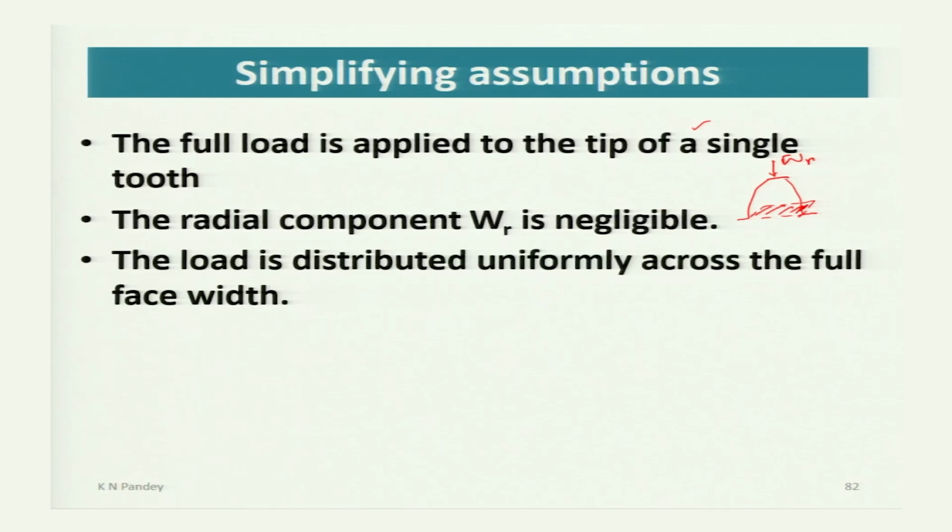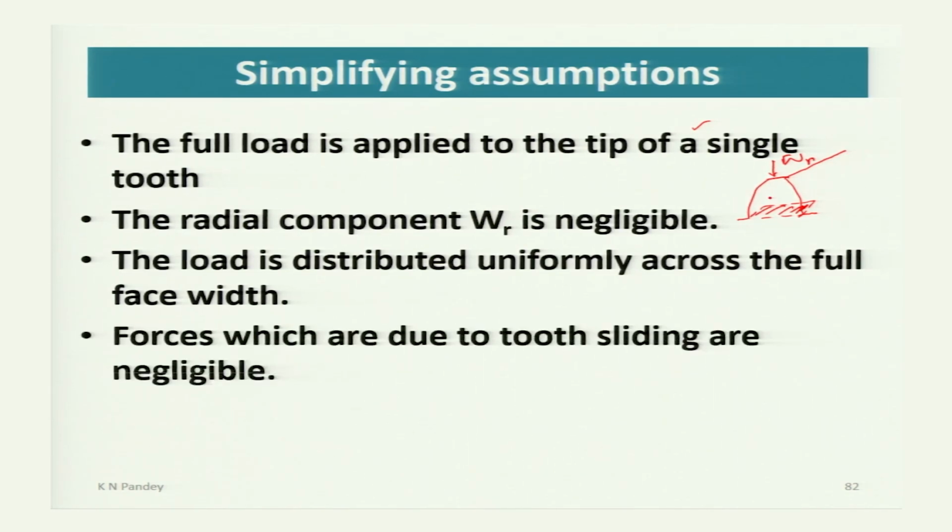The load is distributed uniformly across the full face width. So it was considered that the load which is transmitted, this Wt or the normal load W, is uniformly distributed all along the width of the tooth. Forces which are due to tooth sliding are negligible. Now we know that from the point of engagement A to the point of disengagement B, there is a combination of rolling and sliding when the teeth are under contact.